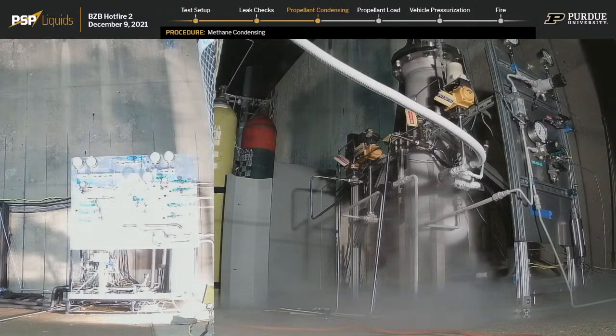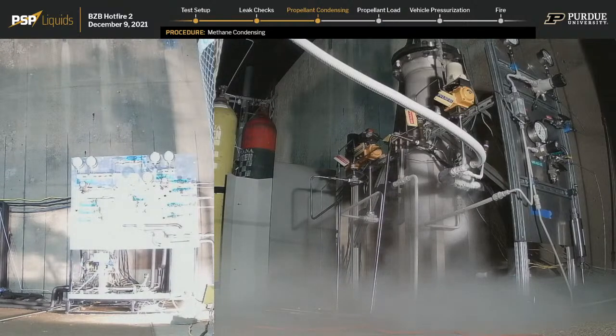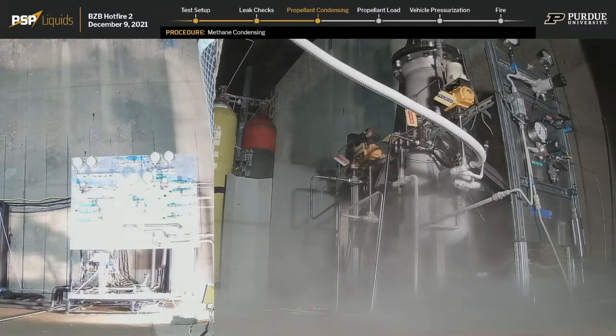And what this is doing is it's sealing off our vent lines so that we can have an exact known pressure, and of course, due to thermodynamic properties, pressure controls the temperature because the temperature is controlled by the boil-off point of the liquid. And as the liquid boils off, it'll build pressure if we have a closed valve. So it's kind of a feedback loop that we need to be constantly balancing.